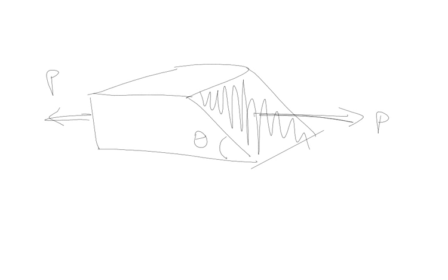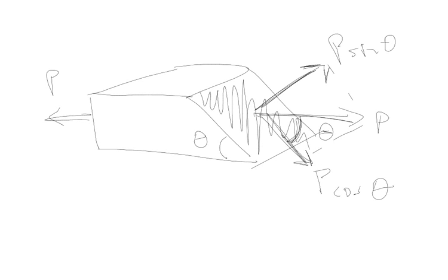Well, there are two kinds of stresses that we talked about. We know there's a stress that's perpendicular to a cross-section. That means it's due to that component of force P. And we know that there's a stress that's parallel to the plane of a cross-section. That's your shear stress. So what are these two forces? Well, you know that they're components of this force P. If that's angle theta, then this is angle theta. So this is P sine theta. This is P cosine theta.